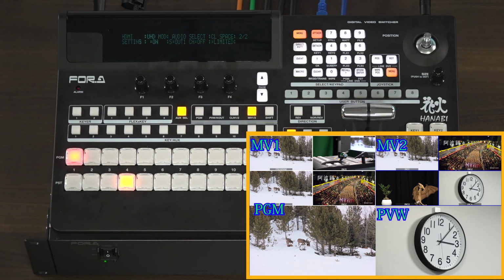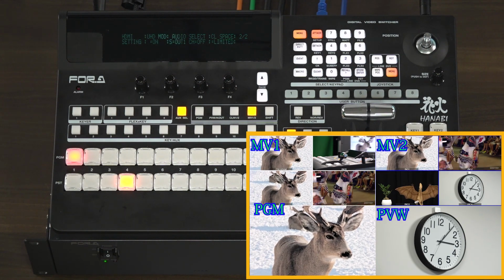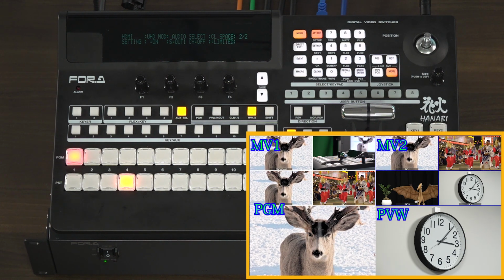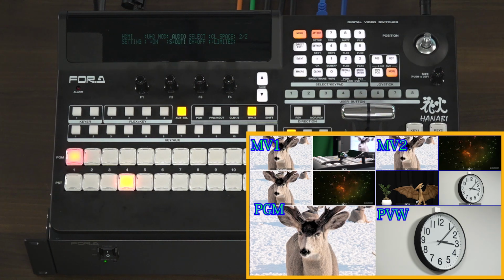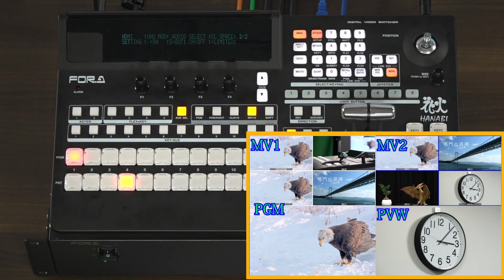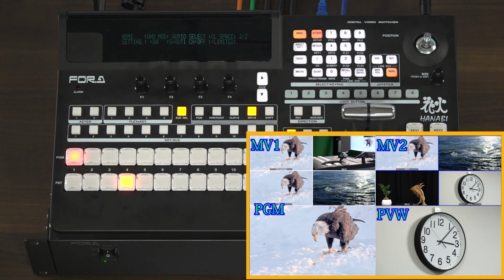In Audio Select, use F2 to select the video signal with audio superimposed that you want to output to HDMI and F3 to select the audio channel to output. HVS-190 can output 2 audio channels to HDMI. Color space allows you to change the color range output over HDMI to suit the monitor used.